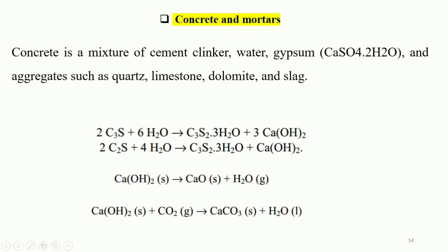It is a crystalline solid, and the hydration products of other cement components are not generally described as producing Portlandite. If thermogravimetric analysis is carried out in carbon dioxide at atmospheric pressure, the first event will be the dehydroxylation at 400 degrees Celsius of any Portlandite present in the recently made concrete.